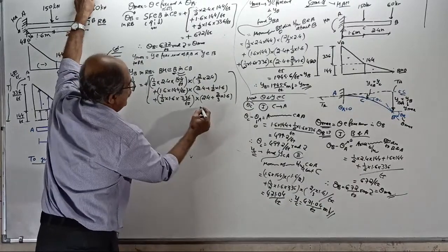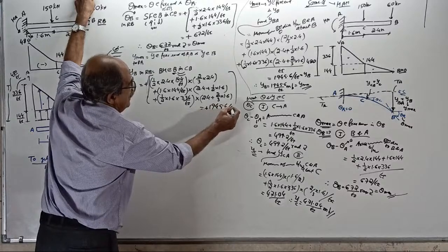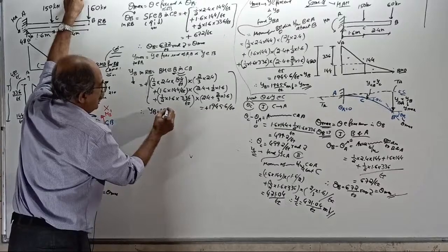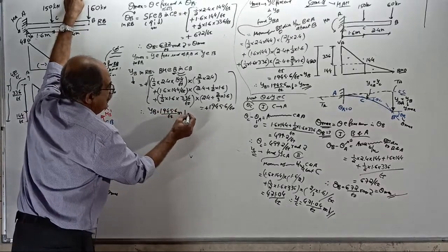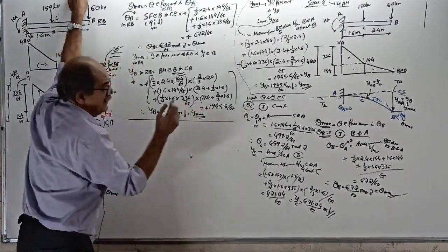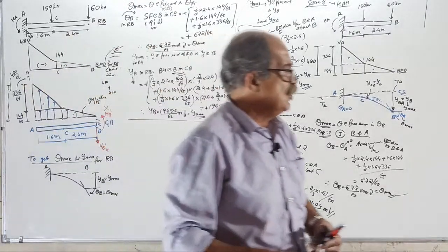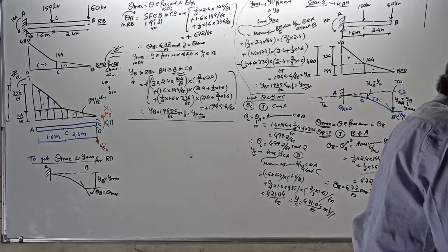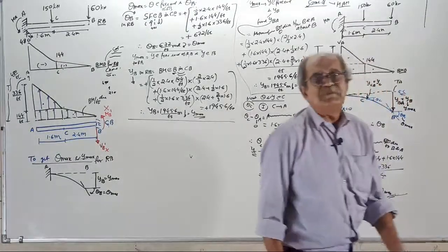Why calculate? It equals plus 1945.6 by EI. Therefore, deflection at B is equal to 1945.6 by EI meter down. That itself is Y maximum. Over. Now, next, be careful. I told you each and everything will tally. Not only maximum, even if you find slope and deflection somewhere else, that also is ditto, in the conjugate beam method and the moment area method for a cantilever.